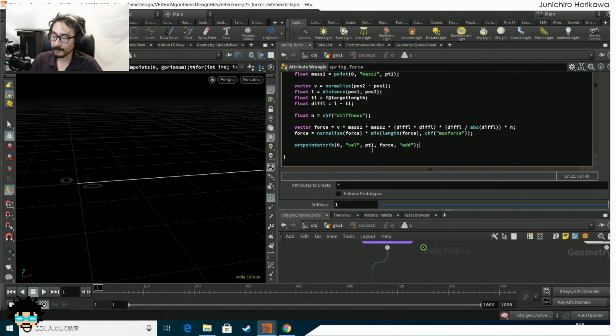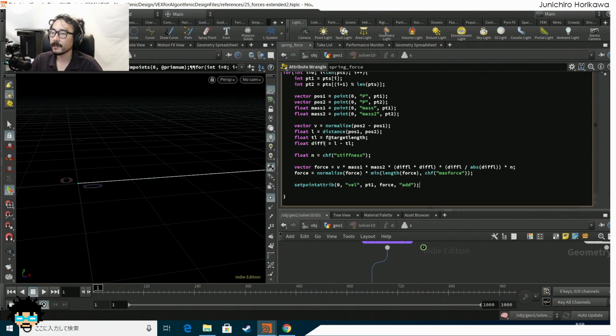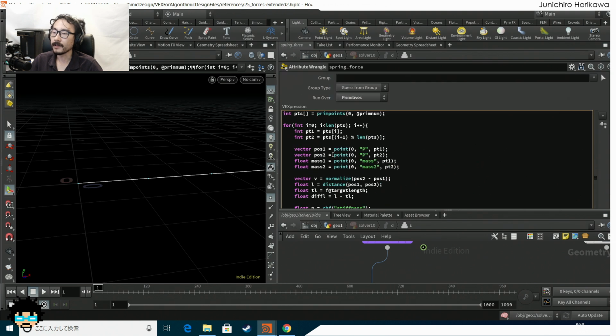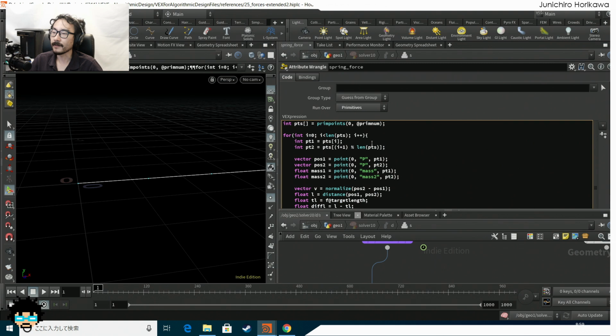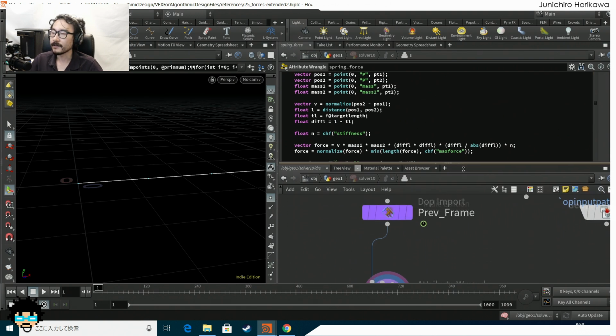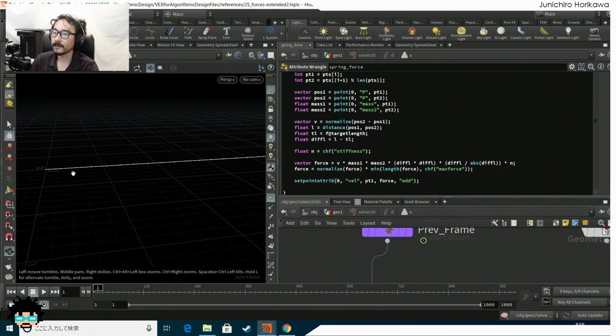so I think this is fine in terms of adding all the velocity into a point. Now I think it's not a good idea to update the point position in this primitive wrangle, because it's simultaneously updating and using this add option for each point. So I want to make sure that all the points have been updated with the current velocity value.